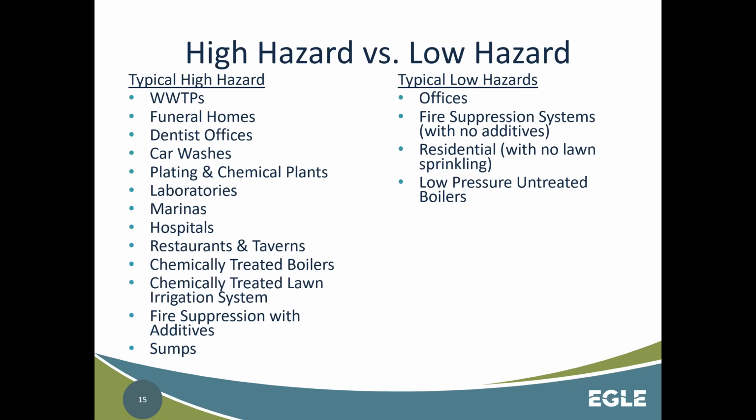So that is something that you as cities need to start looking for is the water assisted sump pumps. They are becoming more and more and more common in these houses, and they're hooked directly to your water system. And a lot of times they get hooked in by either the homeowner or some fly-by-night plumber, and they don't properly protect those and protect the water system. So that's one of the biggest things that you guys, as doing inspections, need to look for in residential.